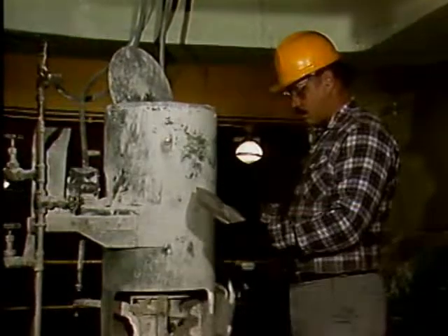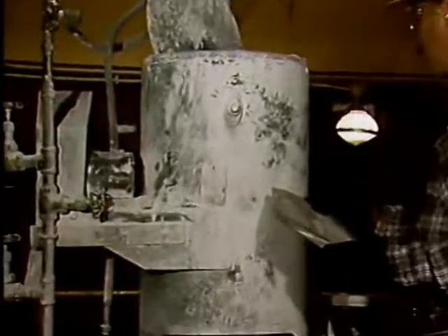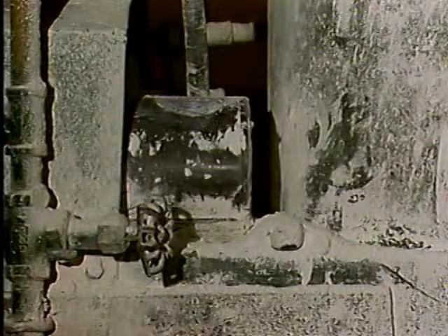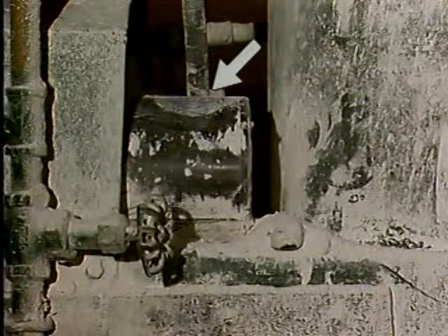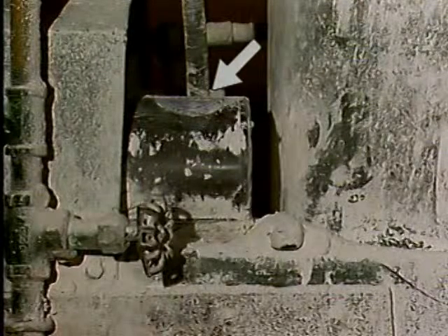After the components that could be causing the problem have been identified, the components can be inspected to locate the problem. In this case, the problem turned out to be a bad electrical connection at the lime shaker motor that kept the motor from operating properly. The P&IDs helped us focus our troubleshooting on the components in the system that could be associated with the problem.